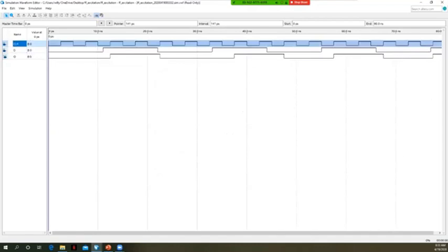Remember, this is rising edge triggered. So we'll only possibly get a change in our output on the rising edge. Here we can see the Q started off as a 0. What I did here is I clicked on clock. You can click on these arrows here and get this little pointer to go to the next time step, the next clock edge.